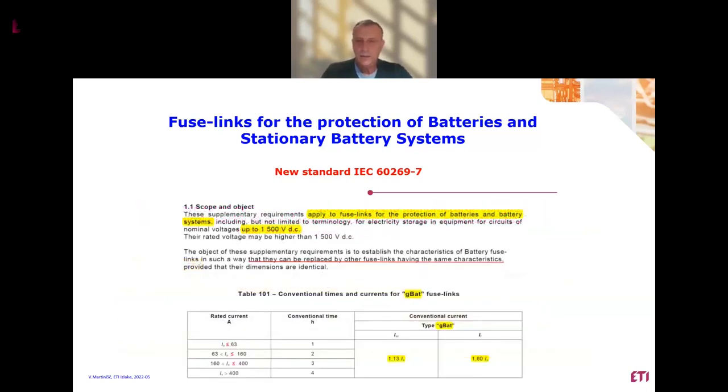There are some other points which are important. Those fuses should be designed up to 1500 volt DC.